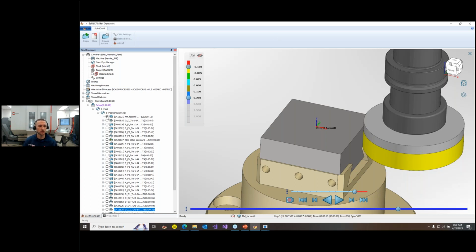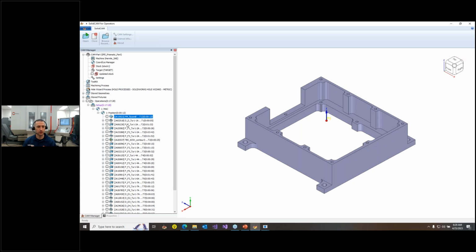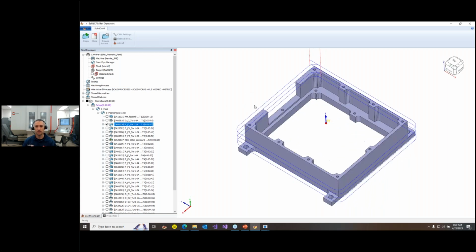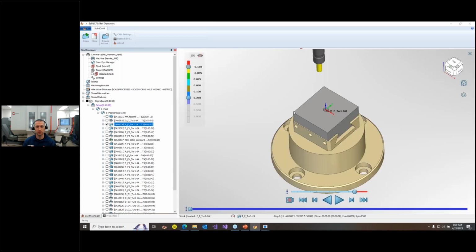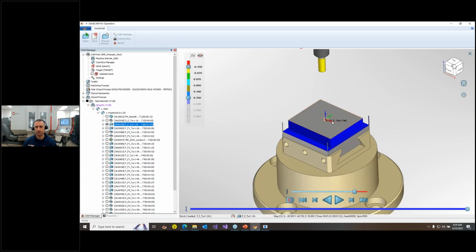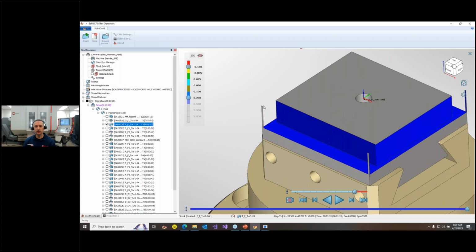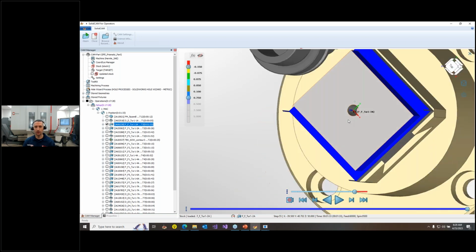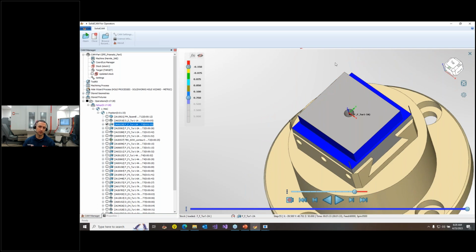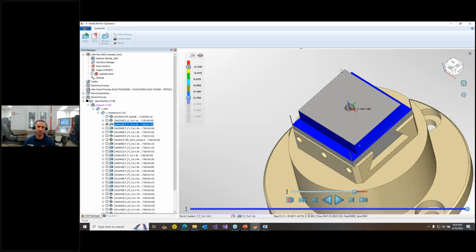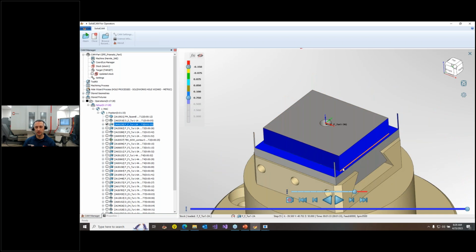Now, I also wanted to show another interesting feature, which I think is this toolpath. Yeah, this is exactly what I was looking for. Here we have an outside cut, and it cuts around the outside. Now, we see we have these little tiny posts that get stuck up on three of the corners. The first corner didn't have one because the lead in and lead out extended tangent, and it cleaned up that chunk. So here we see these little slivers. It's pretty easy to see these slivers, but sometimes in CAM it's a little hard to see these things.